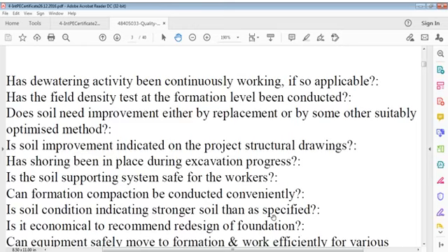Soil improvement, if applicable, particularly in clay soil or silty clay soil, which are not accepted as good soil for the purpose of foundation structurally, they have to think of that. It means should we take out bad soil or unreliable soil to some extent, and then replace that excavated soil with graded soil or a graded material layer. That depends. We can decide on that as a structural designer, or you can say a geotechnical engineer can think on that, whether or not to improve the soil.